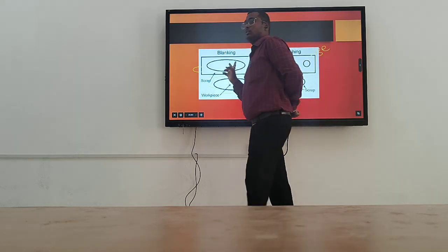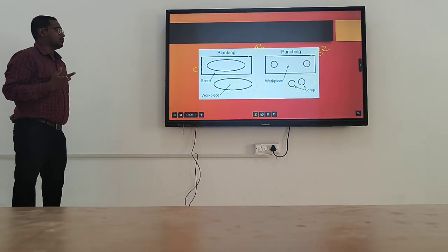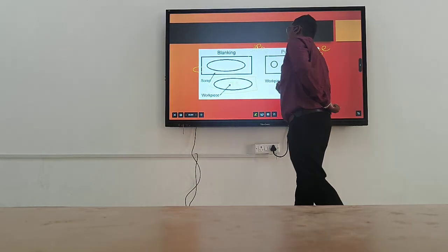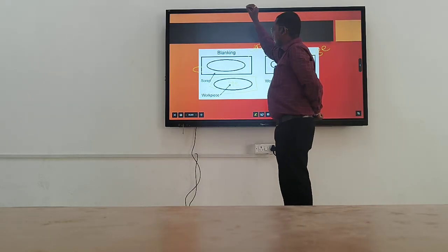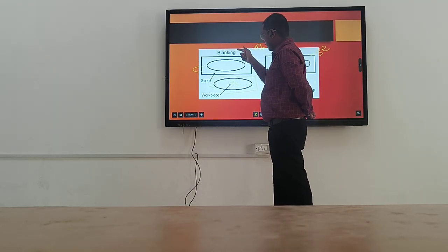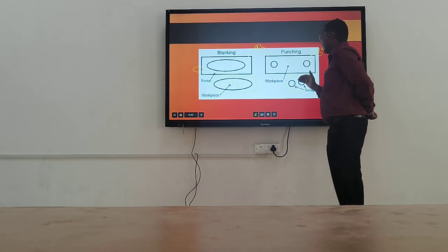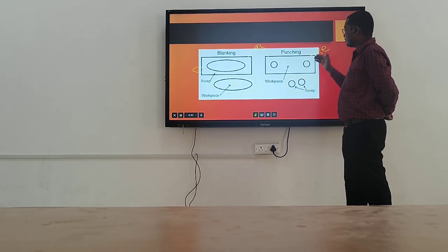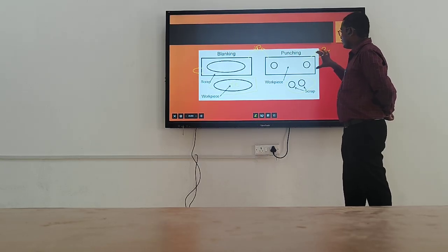Basically, in the exam, questions arise: What do you mean by punching and what do you mean by blanking? Don't confuse them. Blanking means in blanking, whatever product goes out, that's the workpiece. Whereas in punching, the product after punching is the used one. Okay.